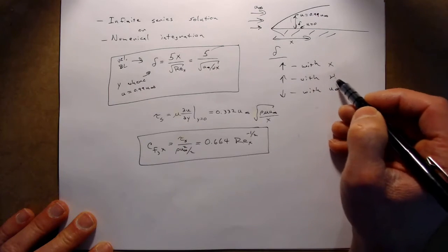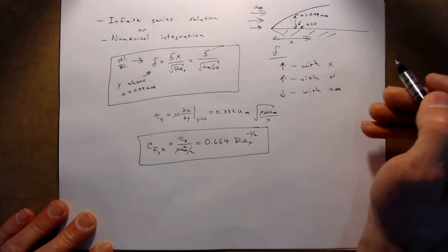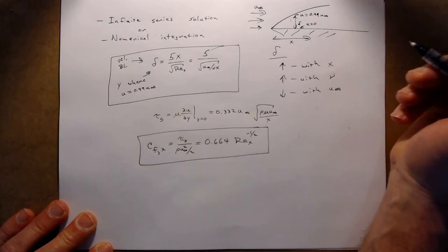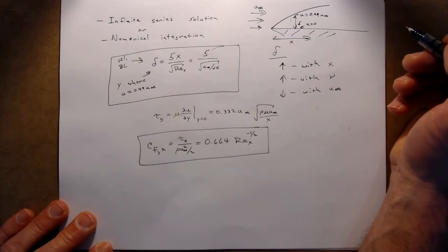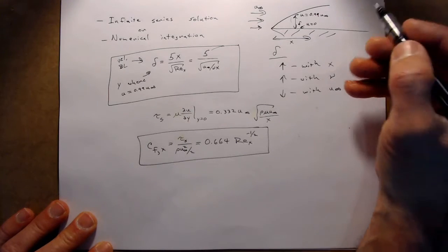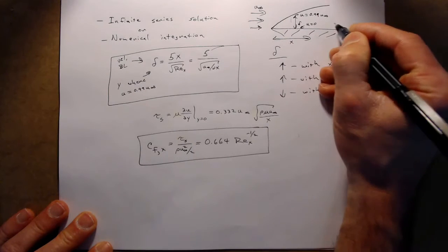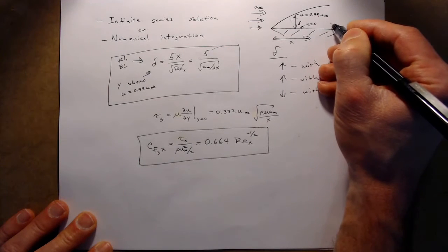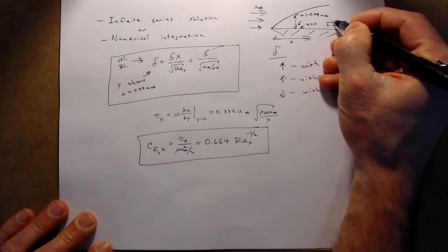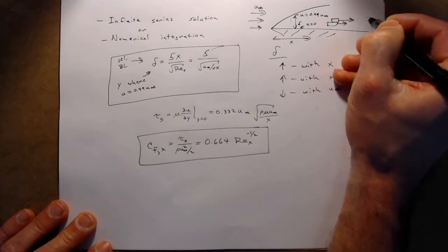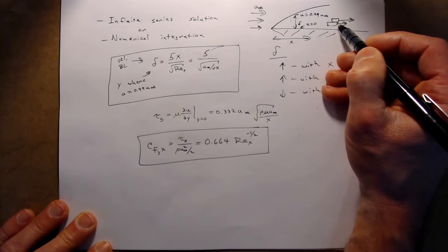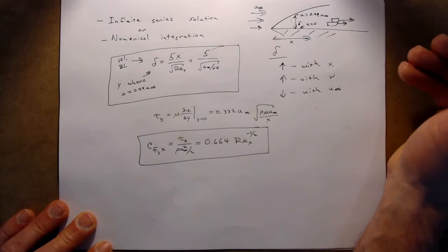It also increases with nu. This makes sense. Nu is our momentum diffusivity. It's the rate at which momentum diffuses down a gradient, or likewise we can think of it as a generalized friction coefficient. It's saying how much drag force the surface applies on a slice of fluid that's trying to move along the surface, or how much drag force two fluid packets apply to each other, or how much drag force a fluid packet applies to another fluid packet that's trying to slide by it.